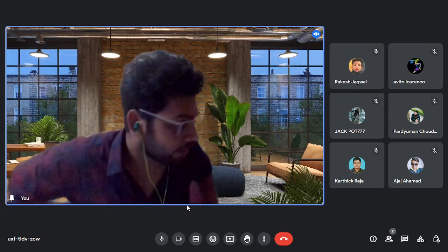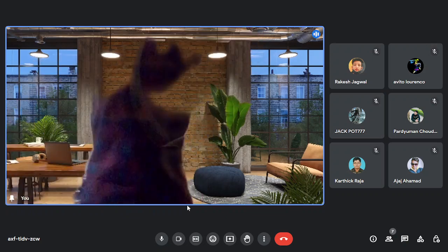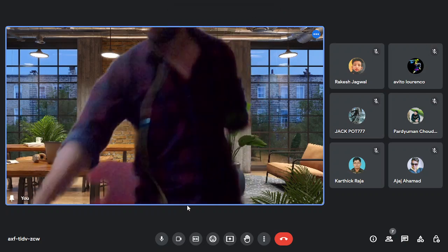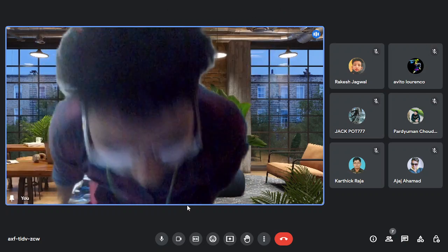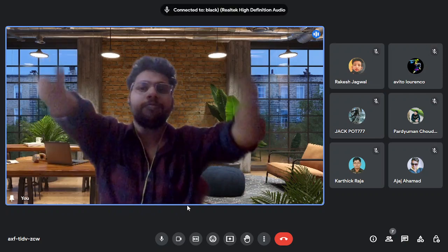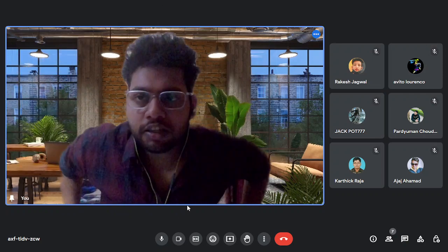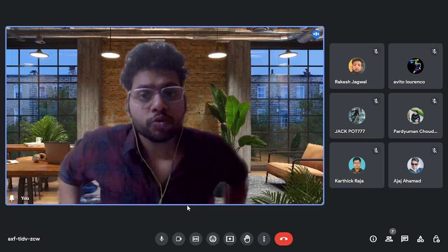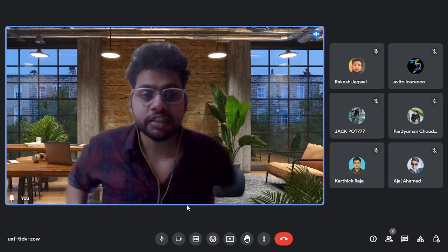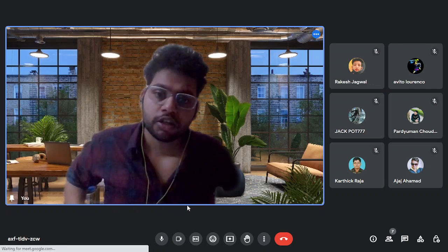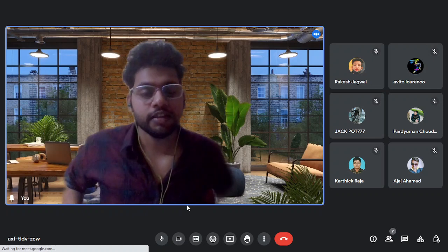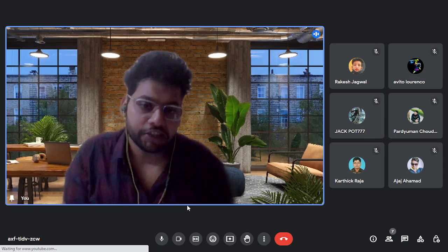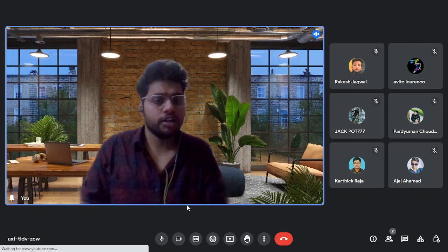That is required to run electrical equipment. We can memorize this concept by knowing that the generator is used to run the electrical equipment. So to run the electrical equipment we need the rating in kilovolt ampere. That's why we use kilovolt ampere for generator power rating, not kilowatt.